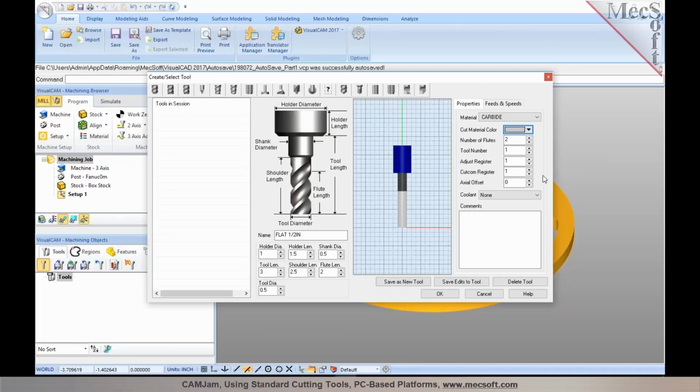And then if you're using cutter compensation, like a G41 to compensate left or G42 to compensate right, some controllers expect you to also output a cutter compensation register like a D followed by the register number. In most cases, you would also set this to be the same number as the tool number, because it points to the table for the cutter compensation register, and the value that you're going to be compensating is what you would enter in the controller's tool table. So basically this maps to the tool table's registers. So you would want to specify these.